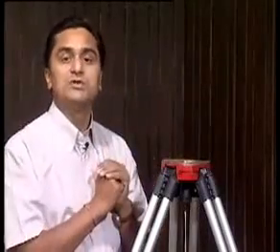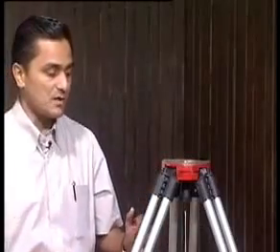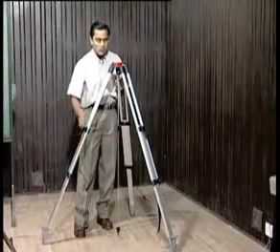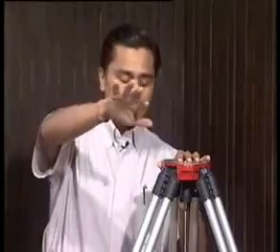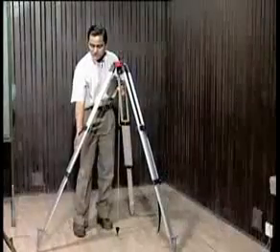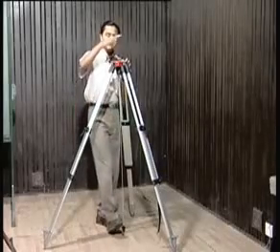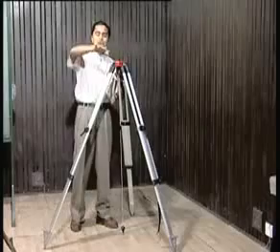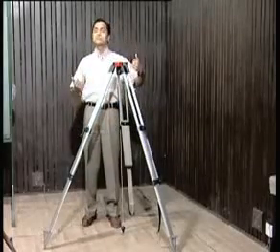It's by visual examination. Now there are two movements of the tripod legs. One, I can move the tripod leg circumferentially. Basically, when I move it circumferentially, what happens? It will change the leveling. It will not change the centering. So if I move it circumferentially like this, generally the centering of the tripod will not change much, while the tripod head will change its leveling. So I can do it for any of the three legs, depending on the requirement.